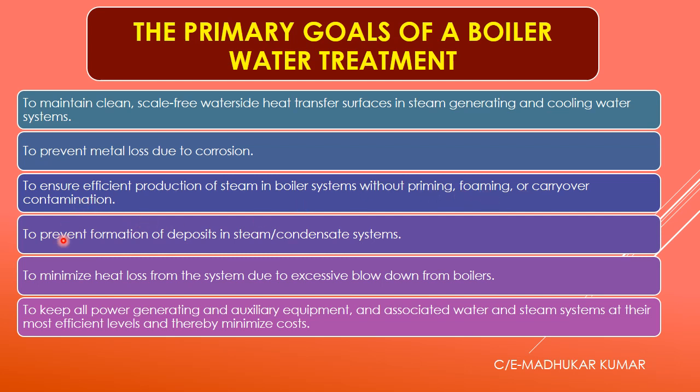Okay, next, to prevent the formation of deposits in the steam and condensate system. Of course, if the boiler water is maintained, the contaminants are less, or time to time the actions taken, that is your blow down and all, so you will have fewer floating contaminants, so less deposits, less scale deposition into the steam and condensate system, and they will be healthy.